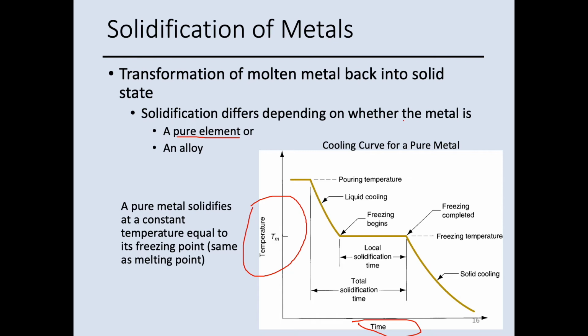Pure metal has different behavior compared to alloy. So here, when the material is cooled down, it gets to the freezing point, where the freezing is going to start, and then at the same temperature, the freezing is going to continue.